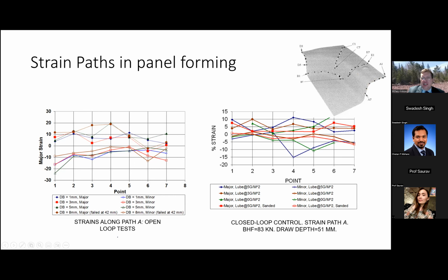What's really interesting is that the strains on 0.7 here look somewhat random, but what we see here is that from 0.6 to 0.7 we have what appears to be convergence in our strains. And so that gave me a lot of hope that we were actually doing indirect strain control while we're controlling on local punch forces.